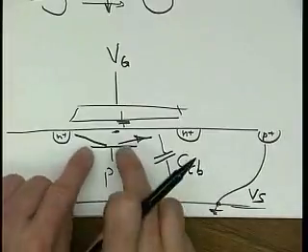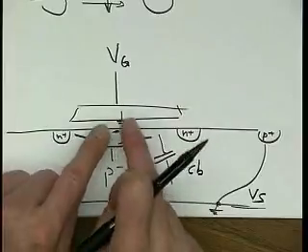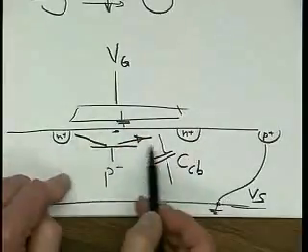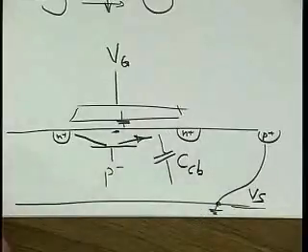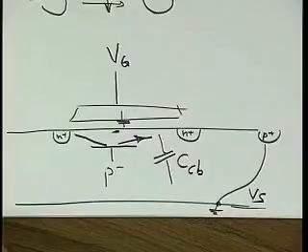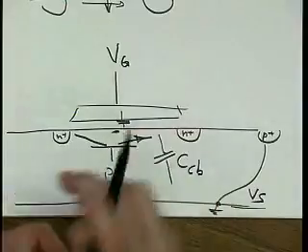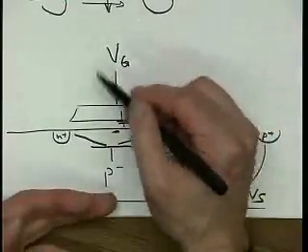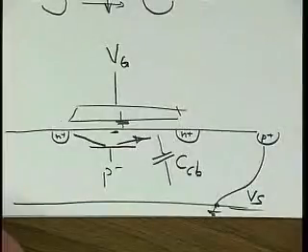Because this is a semiconductor, as we change the potential here, more or fewer carriers go into this region, into the channel region of our MOS transistor that acts sort of like a bipolar transistor. Right? So we actually can modulate the number of carriers that we have in the base of these transistors by varying the voltage on the gate of the device.